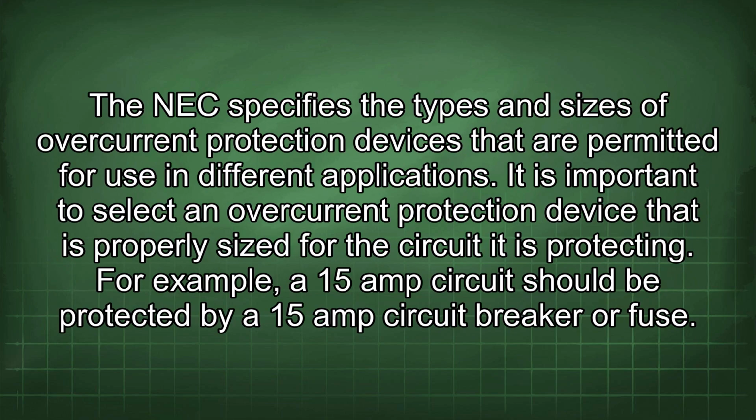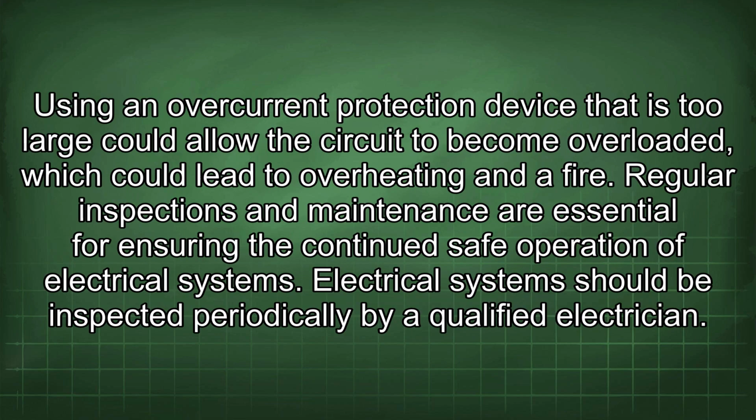The NEC specifies the types and sizes of overcurrent protection devices that are permitted for use in different applications. It is important to select an overcurrent protection device that is properly sized for the circuit it is protecting. For example, a 15 amp circuit should be protected by a 15 amp circuit breaker or fuse. Using an overcurrent protection device that is too large could allow the circuit to become overloaded, which could lead to